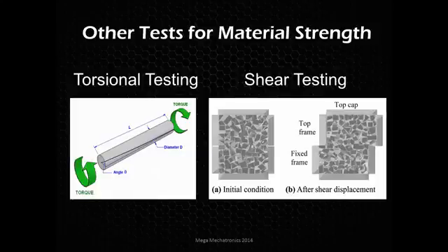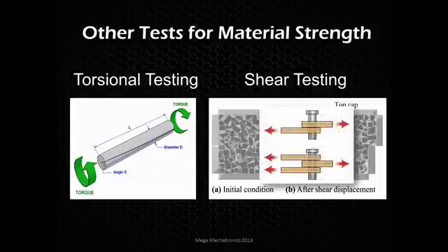So here's a working example of a bolt under a shear stress. That's something you'd test for fasteners. You'd want the shear strength when you're looking up a fastener that will be under shear load.